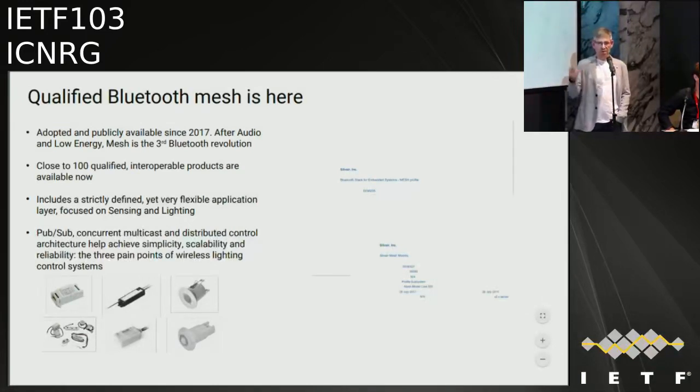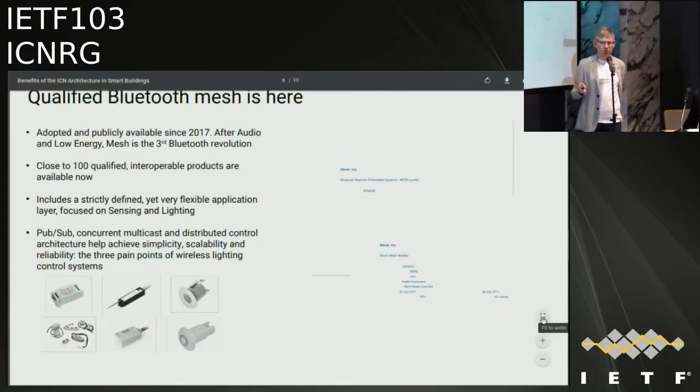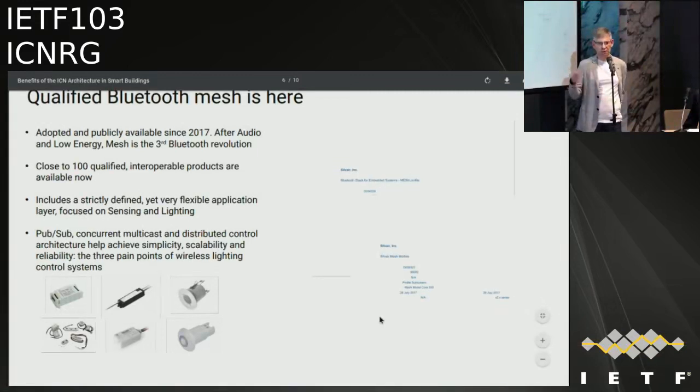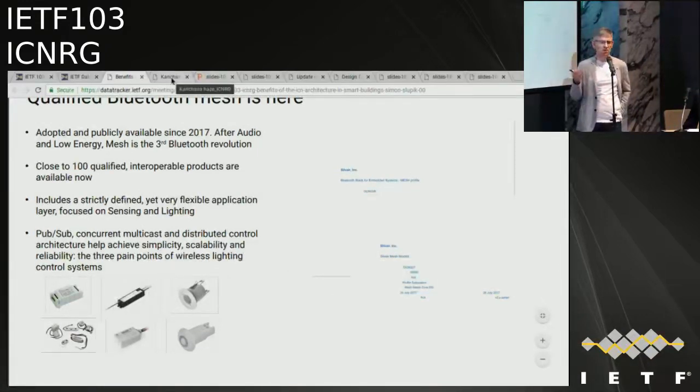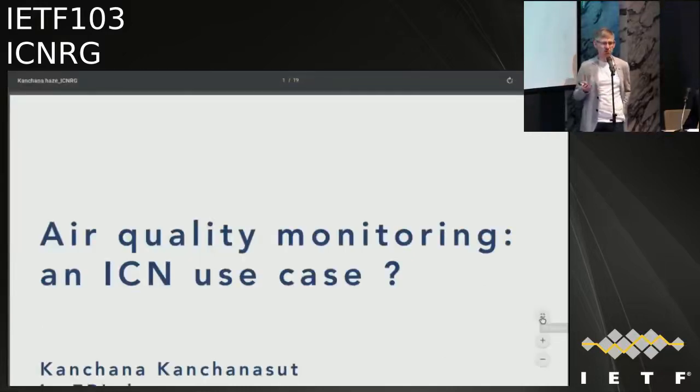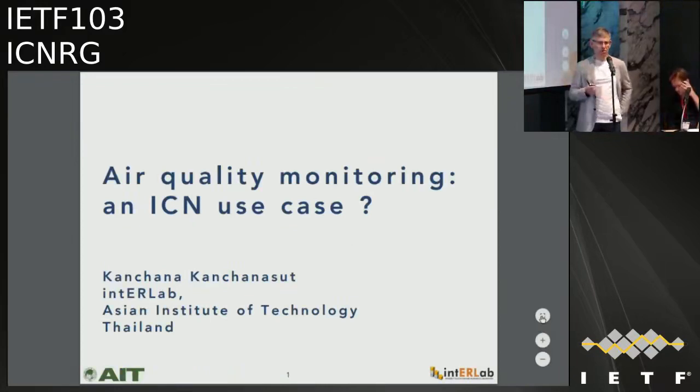Okay. So, for example, for an ambient light sensor in this room, it's unlikely that somebody in the other tower is interested in that information. There may be a gateway, but the scaling factor for gateways currently we see as around 200, 300 messages per second. Ambient light sensors are very talkative, so to speak. They fire a couple of times per second, so if you have a number of them in the room, your airspace fills up quite quickly. So that's definitely leading to a hybrid physical structure, where you have gateways that offload to a faster backbone, and the last two hops maybe are wireless. So you only have routing between the bridges, but yes, a subnet is broadcast. Yes.